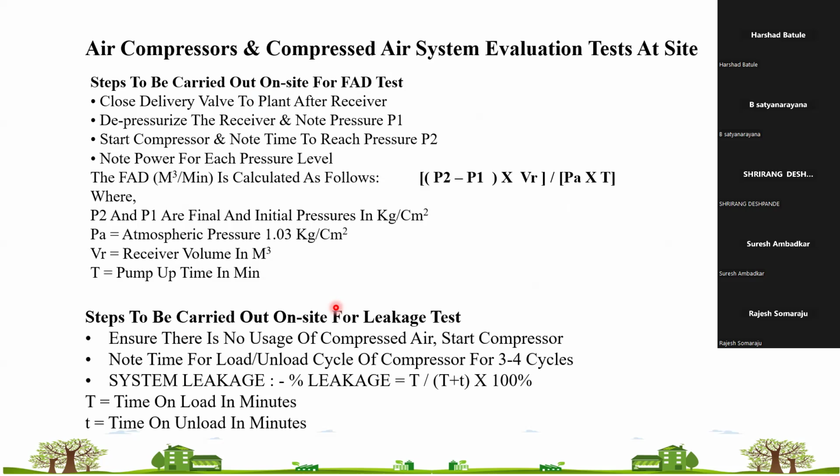So what does isothermal efficiency mean? Isothermal efficiency is the ratio between isothermal power and actual measured input power. How is isothermal power calculated? Isothermal power depends mainly on your pressure ratio and the volume of free air delivery.